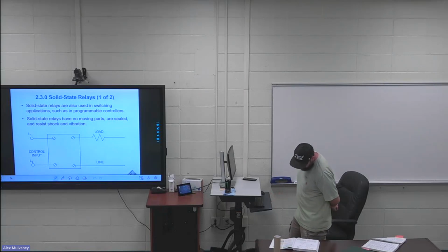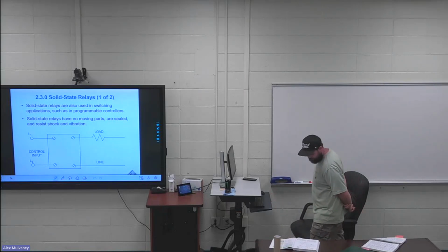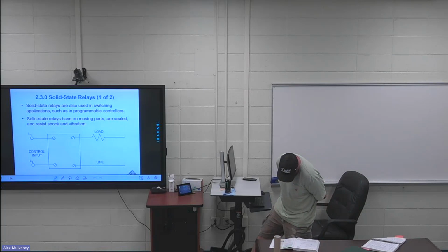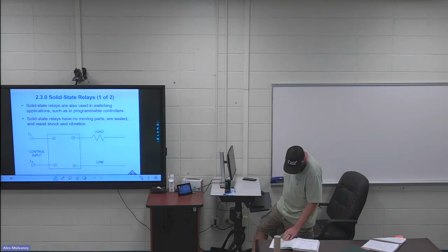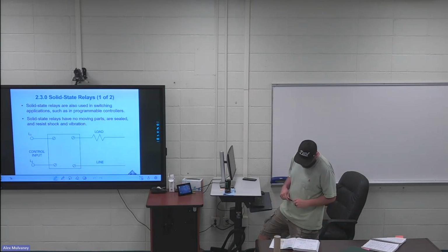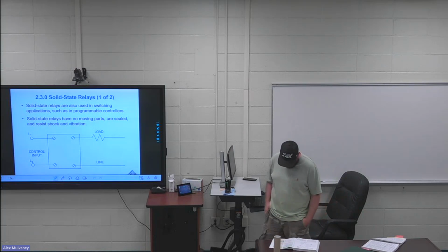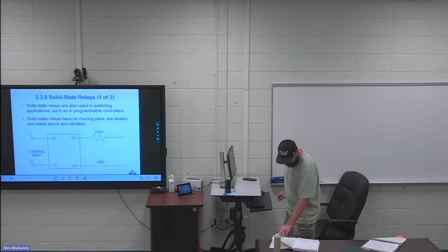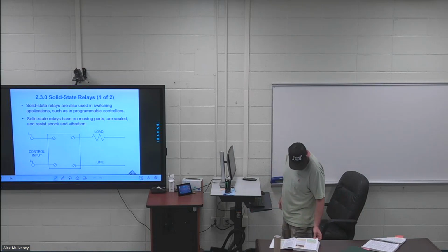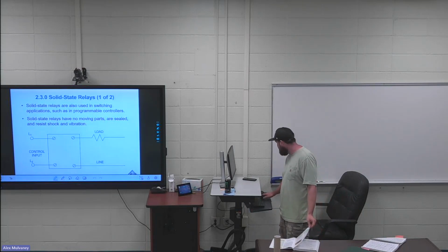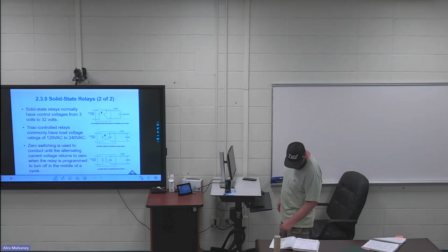Down at the bottom of page 11, right after that note is highlighted, the following are some typical solid state relay control circuits. Almost all of the first bullet point is highlighted. Power transistors for DC loads. In this DC circuit, a power transistor is used to connect the load to the line as shown in figure 13A. So that's the top one on the board.